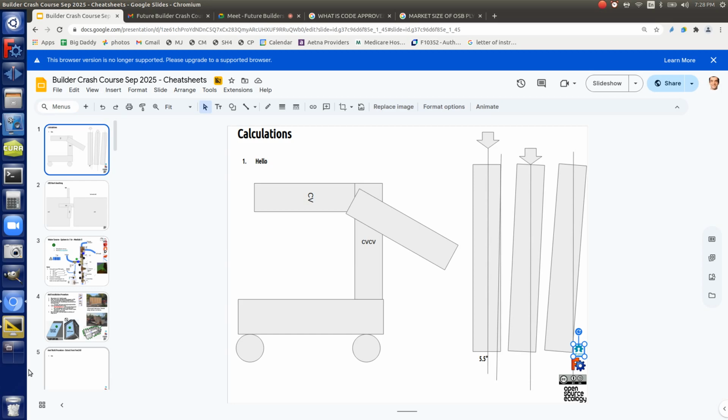If you know those 3 or 4 different orders: steel around 100,000, rock and plastic around 5,000, wood under 1,000, like 300 for standard SPF, spruce pine fir, that's what they call SPF lumber, the stuff at Menards. They rate it at 300 psi.